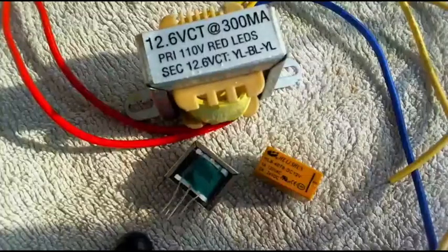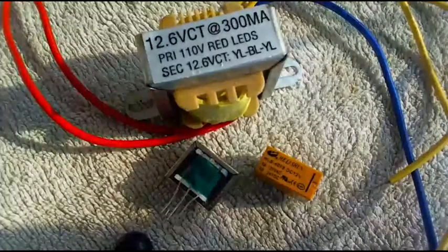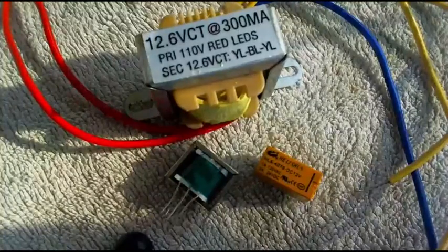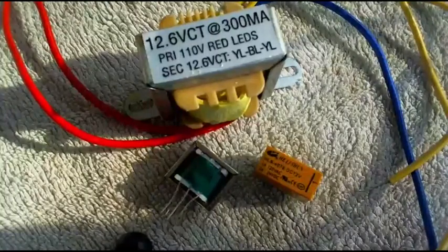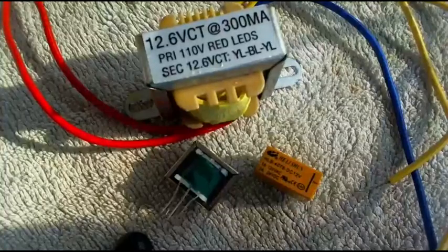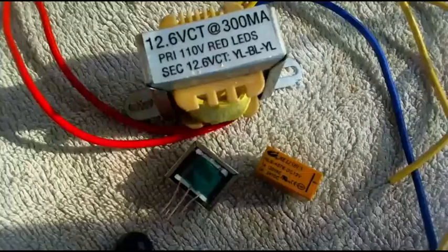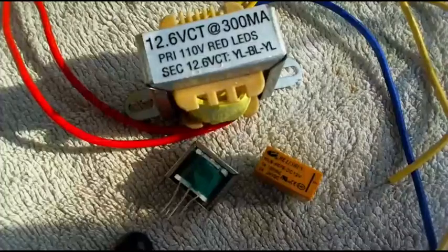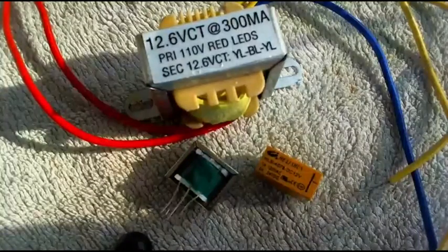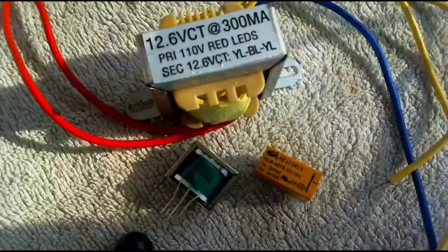So if we have a variety of capacitors for which we know the value, and we can use our function generator, or if you're using a Picoscope, your arbitrary waveform generator, we can set the frequency or scan across several frequencies, know the value of our capacitor, and when we identify a point that corresponds to resonance, we then have F resonance, and we can go back through our resonance expression and basically use basic algebra to solve for the value of inductance.